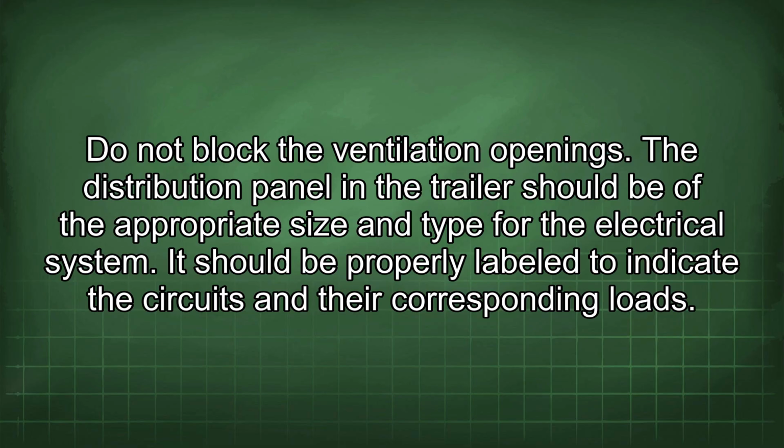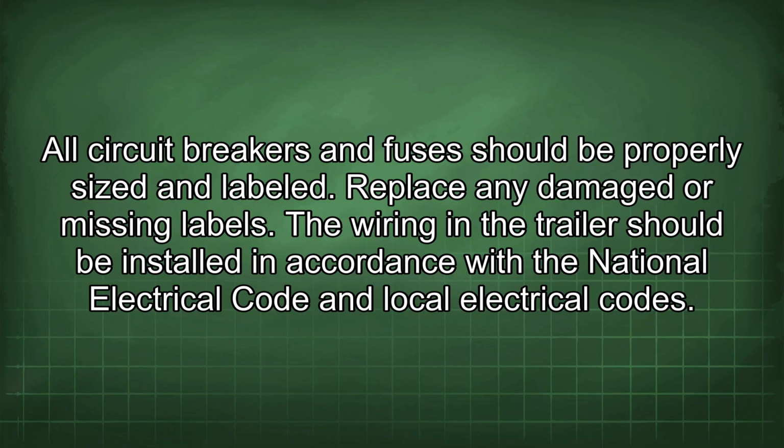The distribution panel in the trailer should be of the appropriate size and type for the electrical system. It should be properly labeled to indicate the circuits and their corresponding loads. All circuit breakers and fuses should be properly sized and labeled. Replace any damaged or missing labels.